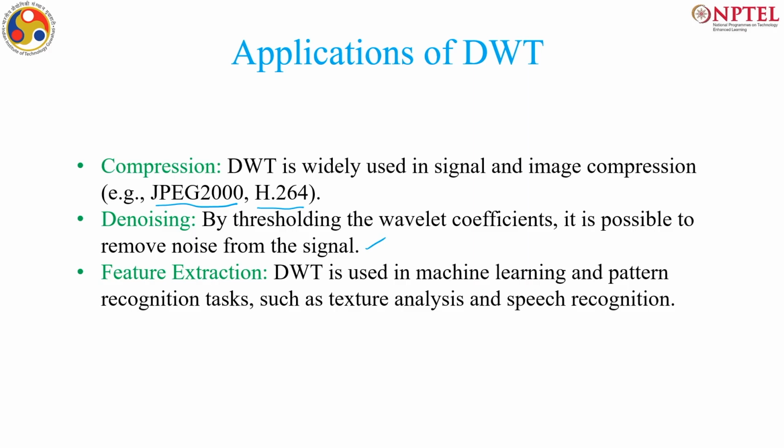Then in denoising wavelets are very nicely used. You see a lot of research papers, many people are using wavelets specifically for biomedical signals, and they are getting really good results. So, noise is usually high frequency components. So, usually if you see the detail coefficients, and if you can do some kind of thresholding, you can very nicely denoise such signals. And then feature extraction.